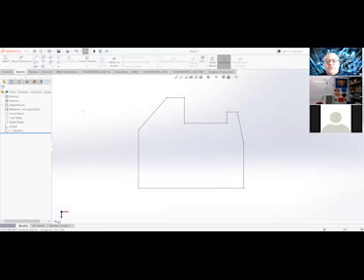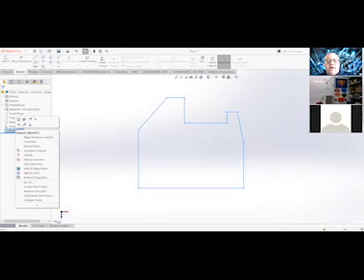I don't want another sketch. I want to finish what I'm doing. So to get back, come down your directory tree and find your sketch 1. Notice it'll highlight your lines with an orange, saying this is what you're picking. It gives you a kind of preview. Then right click, and you have to be a little picky here, okay?